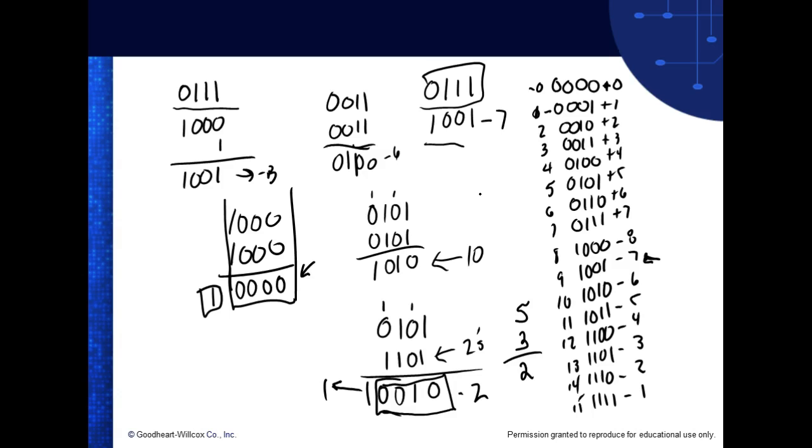Now what's nice about your PLC, if you don't display this in binary, Allen-Bradley is going to display it in decimal. So if you want to put in a -52, by George, all you do is put in a -52. And then the PLC takes care of converting it to 2's complement.